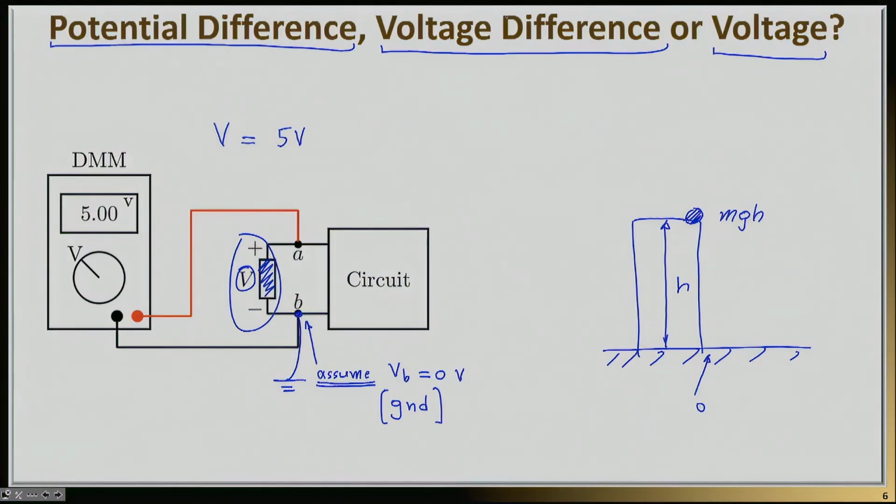In fact, the convention in all the circuits we're going to be seeing later on in this class is that typically the bottom layer of the circuit will be assumed to have a 0 potential, and everything else will be referred to this potential. So with the assumption that VB is equal to 0, we can basically say that VA, which is nothing else but V minus VB, is going to be equal to 0 volts.